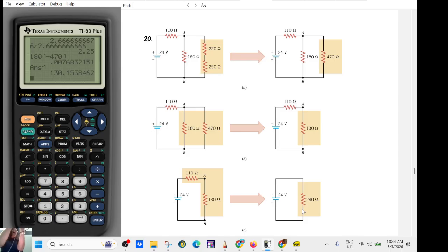It's not the voltage that kills. And then I can take a fluorescent light, and it should light up. Can you see that? Isn't that good? So I am at 0 volt because I'm connected to the ground. This is 1,000 volt. And so you apply a voltage. You see, it's highlighting only this part. So there is a tiny current flowing, exciting the electrons of the mercury.